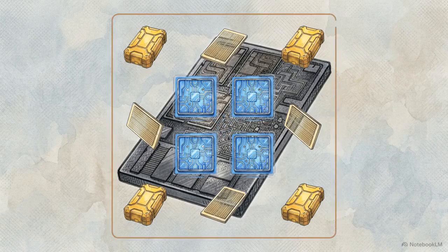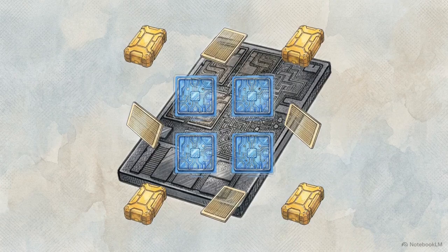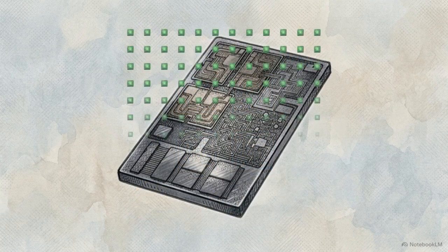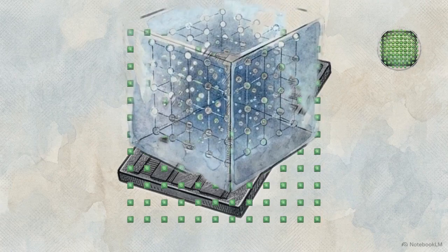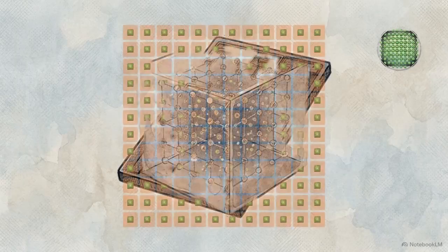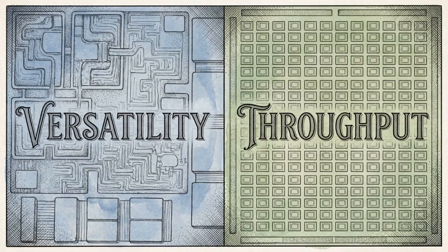The GPU architecture uses that same silicon real estate to achieve a different objective. By stripping away the complex control logic used by the CPU, engineers fit thousands of smaller, simpler processing cores onto the same footprint. This trade-off is effective because massive parallel workloads avoid complex branching logic. They only require executing repetitive mathematical operations in perfect unison. Physical allocation determines capability. Investing silicon in control logic yields versatility. Investing it in core count yields throughput.